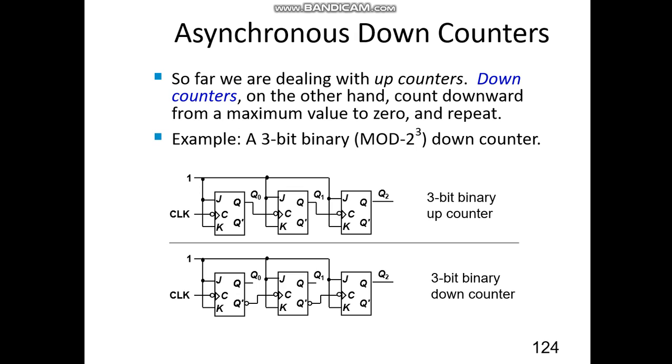But the design of asynchronous circuits is always complex, because each state is fully controlled by the previous flip-flop. You have to define the previous flip-flop state and which value we give to the next clock pulse. That is the up counter and down counter. Using switches, we can define an up-down counter in the same circuit. For the first mode we use up mode, the second will be down mode. That is a universal asynchronous ripple counter, as we discussed.